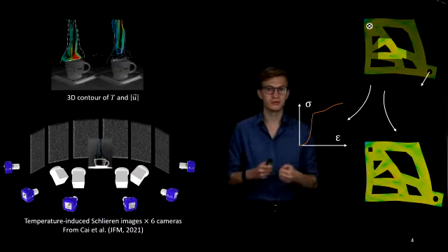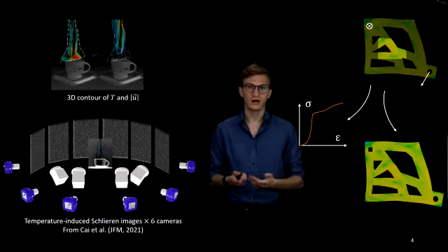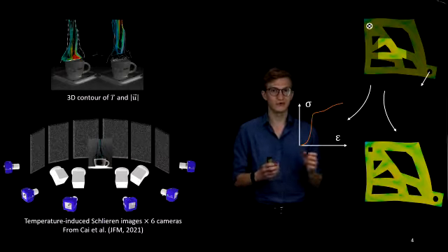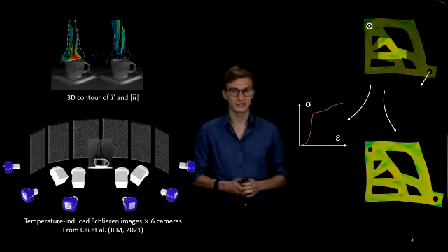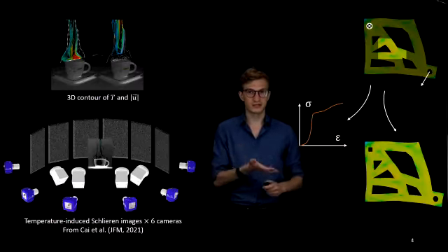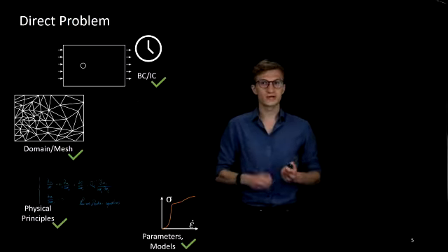For instance, it can be the Young modulus, it can be the Poisson ratio, or a more complicated constitutive relationship, like is illustrated there. And this with only experimental data that can also be imperfect, and we'll see that in a few slides. Okay, so the two last examples that I've presented there are perfect examples of inverse problems, and these are opposed to direct problems.